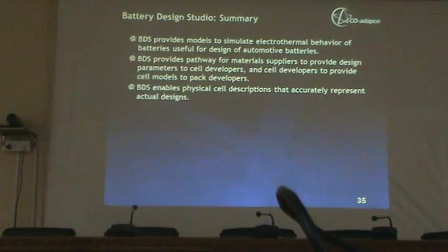Yes, so I hope you got a very brief presentation on the capabilities of Battery Design Studio. It's a 1D tool where you get the electrochemical properties of the cell, and if you're running a charge discharge cycle, you get them from the software once you give the load accordingly, and you get a lumped temperature value. So the temperature or heat release is averaged throughout the cell, which is resolved in detail when you move to a module-level analysis, when you couple it with STAR-CCM+.